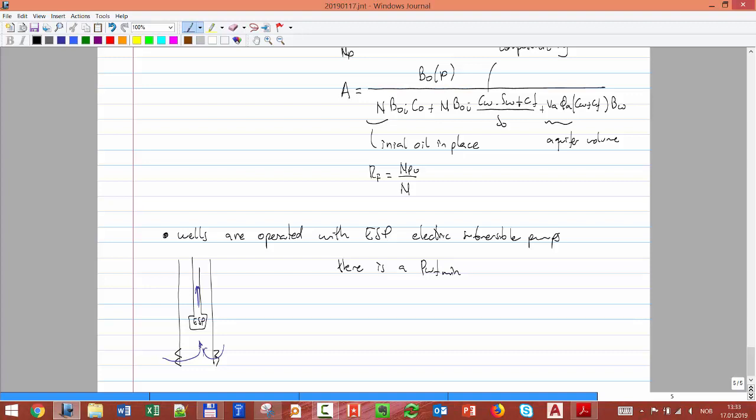Just like in the gas in the previous example, there is a PWF minimum. And that minimum pressure is given in this case by the bubble point pressure at that temperature, because I don't want to get any gas into the pump. I just want to get purely liquid. You can change it to any value, but the minimum you can reach is such that I don't get any gas bubble here. I don't want any gas entering the pump because it won't work.